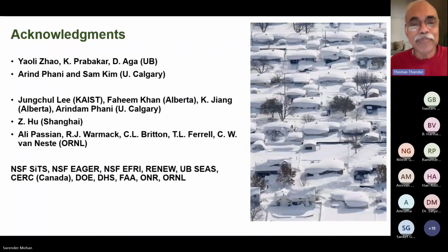Some of these cantilevers are made piezo-resistive. That means when the cantilever bends, the resistance changes, and that can be used. You can use a Wheatstone bridge to measure the bending with respect to a standard cantilever. If the cantilever is bending, its resistance will change because of the piezo-resistive effect. It's not very complicated electronics, but you have to be careful to make sure that noise and things like that are taken care of.